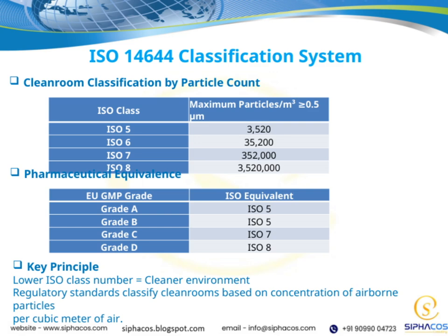This classification system, known as ISO 14644, helps us understand and control the cleanliness of a cleanroom environment. It's fundamental to ensuring the quality and safety of pharmaceutical products. Remember, the lower the ISO number, the more stringent the control, and the cleaner the environment we're working to maintain.